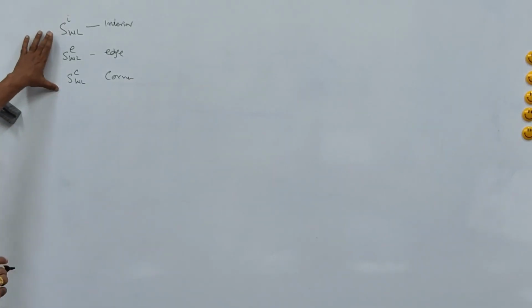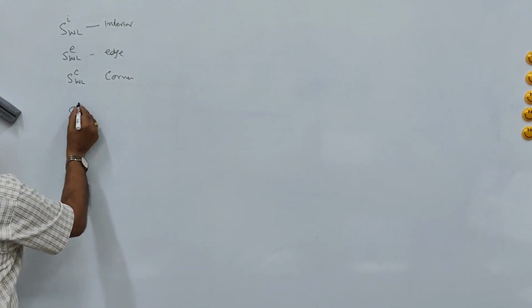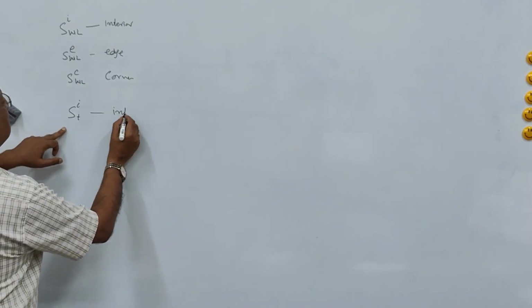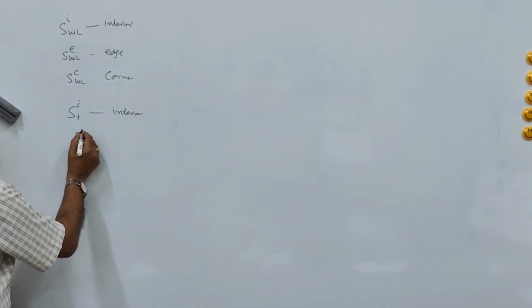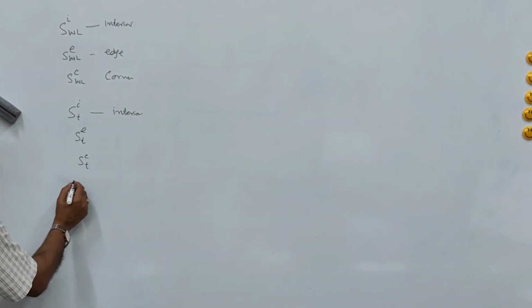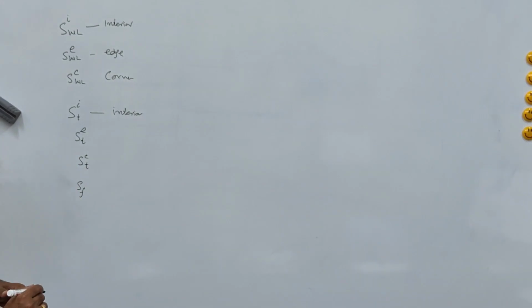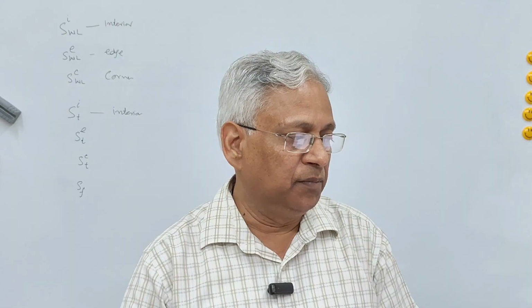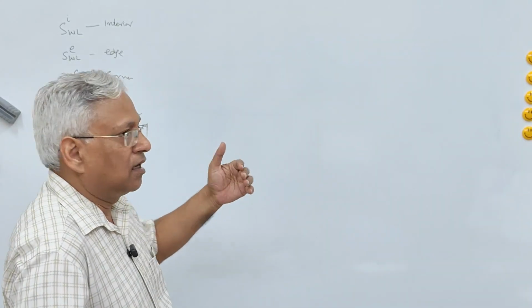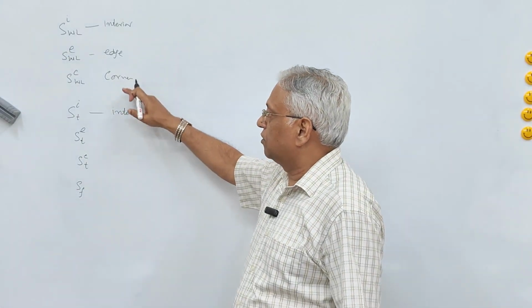And similarly, for temperature stresses, warping stress at interior, temperature stress at interior, at edge, and at corner. And one more, that is frictional stress because of friction. So question is the critical stress combination in the concrete slab during a summer midnight will be, and there are 4 options. Now here we should understand how these stresses are developed at different locations of the slab.